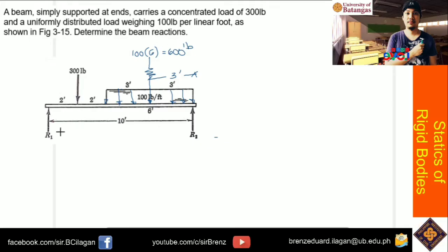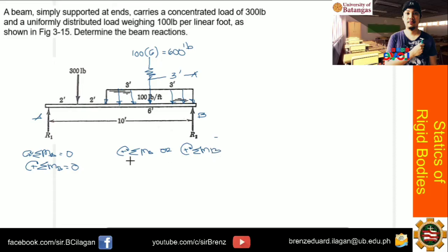The working equations we will use: let's say this is point A and this is point B. We can use either both summations of moment, moment at A and moment at B, or I can show that the same results should come out: take moment at either A or B, and the other equation is summation of forces in y. So moment A or moment B, and summation of forces y. We should still arrive at the same answer using these two options.